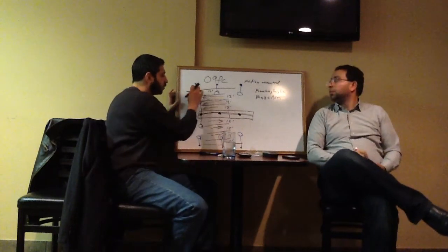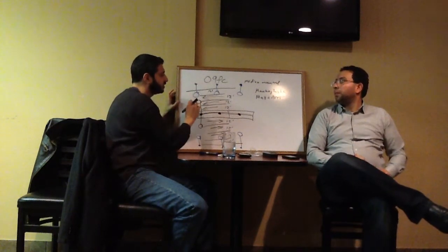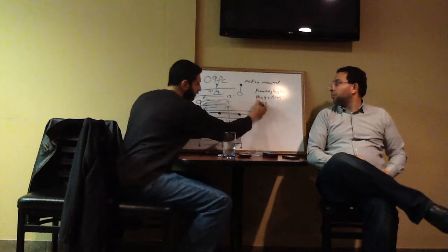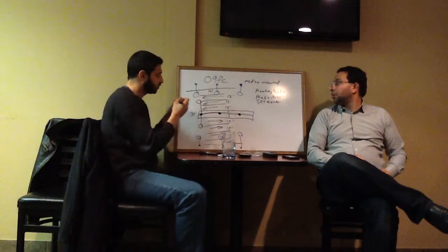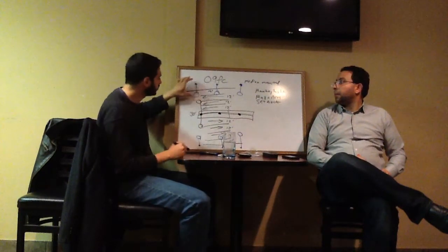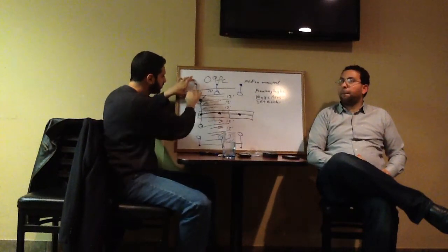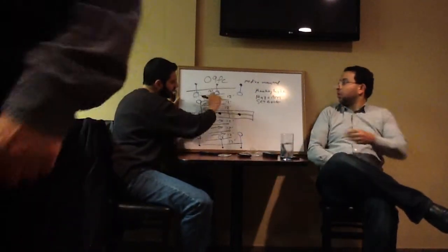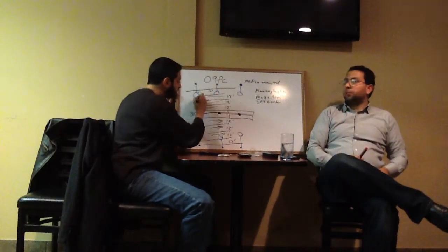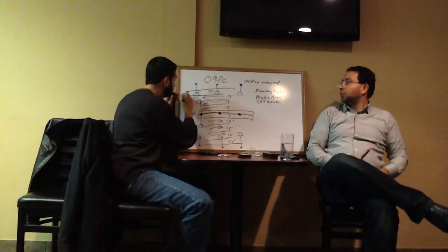So if we do a 15-foot mast arm, what you want to try to do is keep that either over the shoulder or further behind. Setback is usually measured from the edge of pavement, and that's this line here.